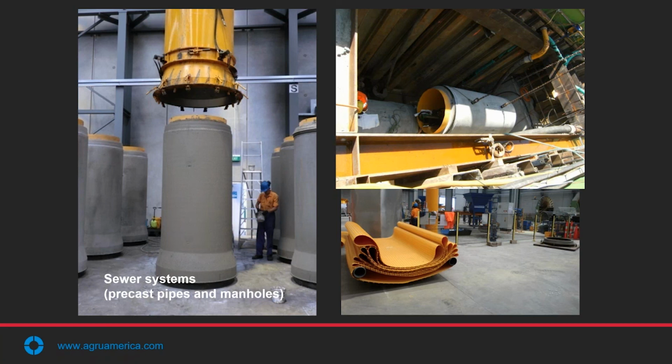So here you see a precast pipe that has been lined with concrete protective liner. In this case, on the bottom right, you'll see that the tubes were formed up, probably using a butt welder. They can be slid over the inner formwork for the precast at the precast plant, and then the concrete is cast between the inner and outer formworks, and the Sure-Grip concrete protective liner is integrally cast into the pipe. Very similar methodology for manholes and other precast structures as well.